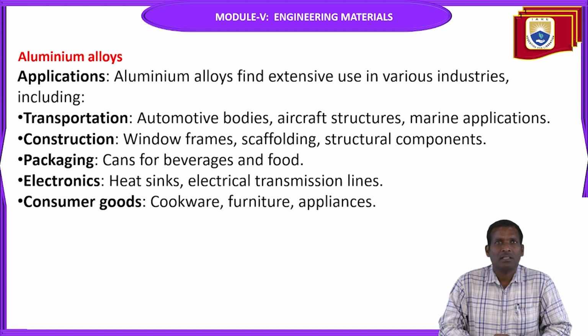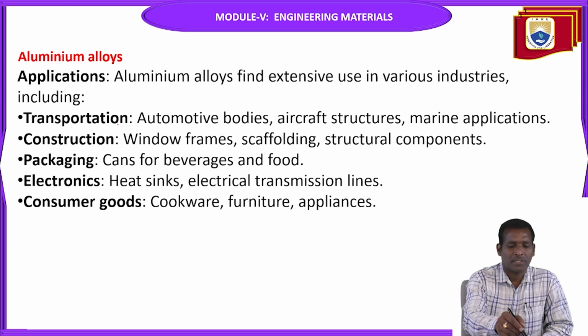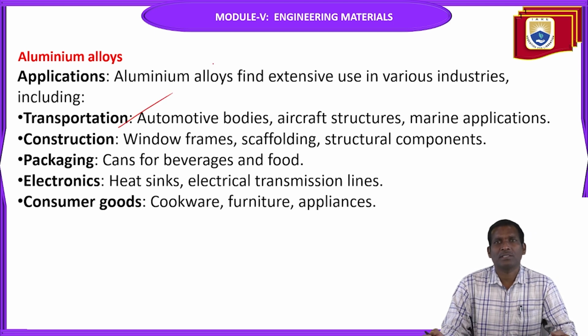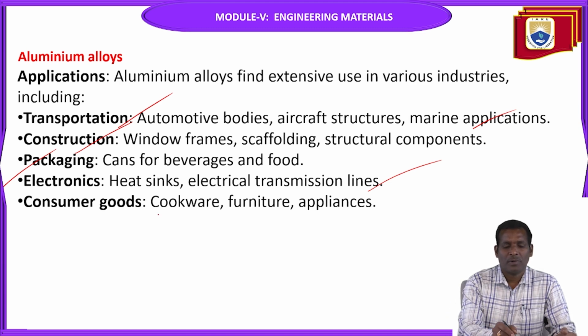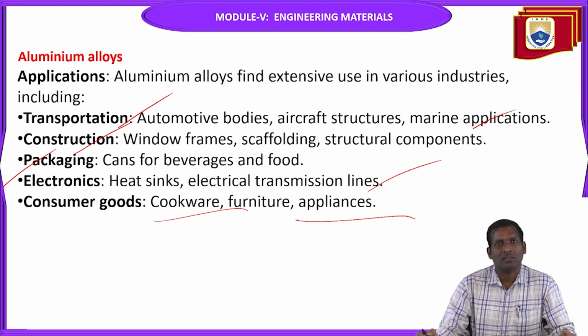The applications: aluminum alloys find extensive use in various industries, including transportation, automotive bodies, aircraft structures, and marine applications, and the construction field, window frames, scaffolding, structural components. Next, packaging, cans for beverages and food, electronics, heat sinks, electrical transmission lines. Consumer goods, cookware, furniture, and appliances.